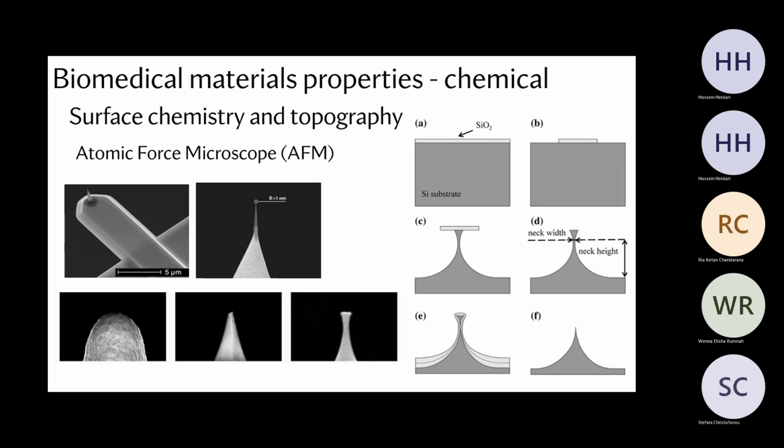And with light, as you saw in the printers, you can narrow it down to a very small fraction of the wavelength of light. Now, the wavelength of light that we use here is 400 nanometers. So we can't go to this resolution, but they use X-ray and deep UV to reach 1 and 2 nanometer resolution pixels. So they put a layer of resin on top of that, they patterned that and removed the uncured material, and then they attacked the silicon oxide with the first etching material.